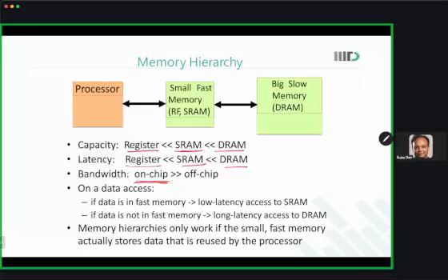For example, let's say I want to copy the whole DRAM content to a hard drive. Bandwidth will decide how much time it will take. Now, if I want to read or write a particular byte or word in the DRAM, that is latency.